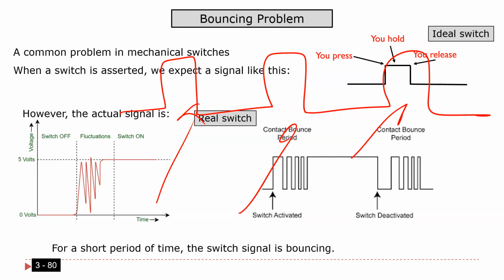If I connect this one to an interrupt, to make only one interrupt, you are not going to make one interrupt. You are going to make 3, 4 interrupts every time you press. The processor is going to think that you pressed 4, 5 times, because processors are very fast. So the processor comes here to check, and finds, yeah, you did one press here, one press here, one press here. Okay, guys, any questions?